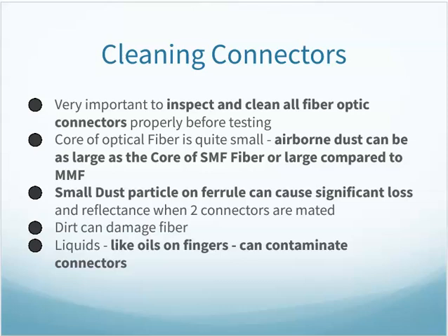They remind us cleaning connectors is super duper important. As we do our testing lab this week, most of the things we're going to test, we're going to clean the connector before we hook them into the tool or the meter and so forth. There is one time that I'll have you purposely touch your finger to the end and then see what it looks like under the microscope so we can see some of these things they're talking about. So they're reminding us to clean all the fiber connectors.